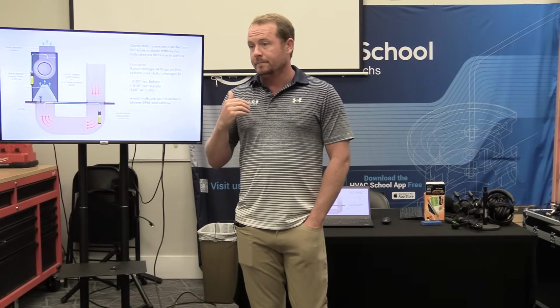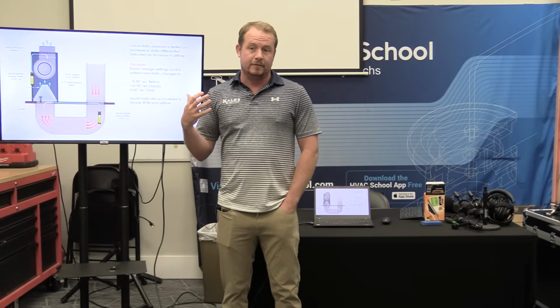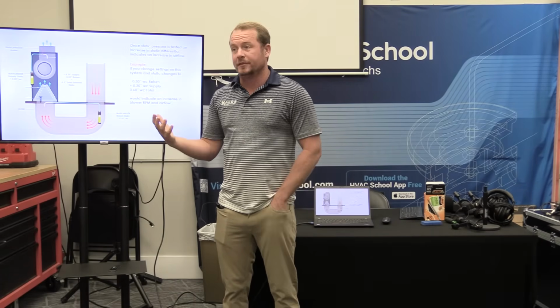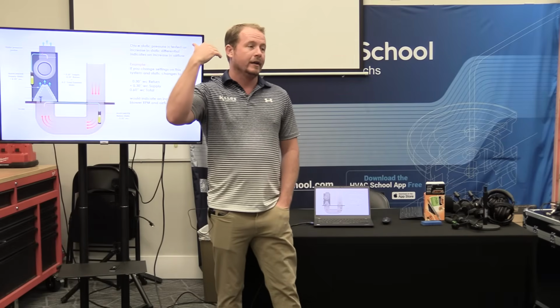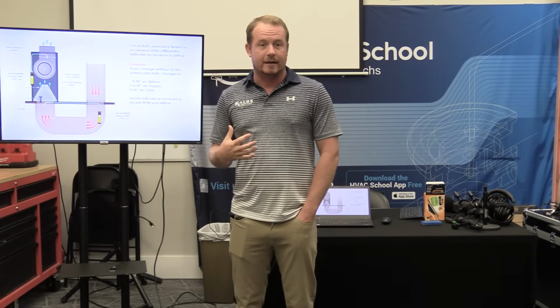You're doing something like replacing a blower motor because one failed. Now's a really good time to go ahead and check that. You have an airflow problem with the system, or you have a system where you are running something like low superheat and low suction pressure, so it's an indication of low airflow. Now's a good time to check it.